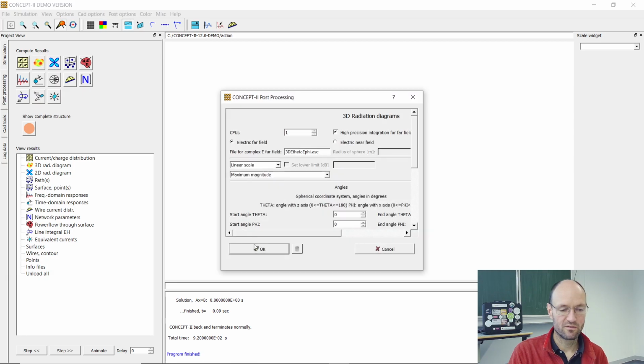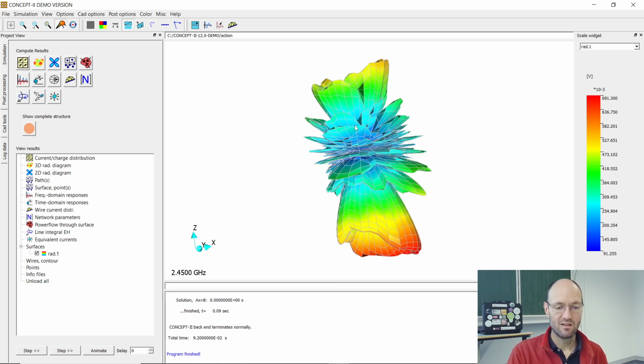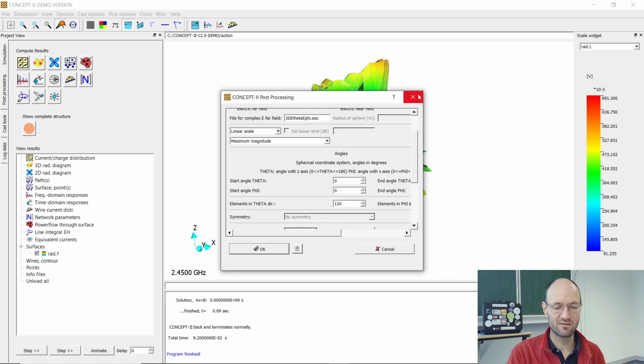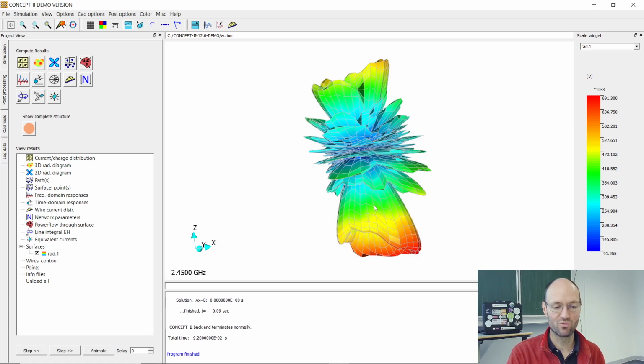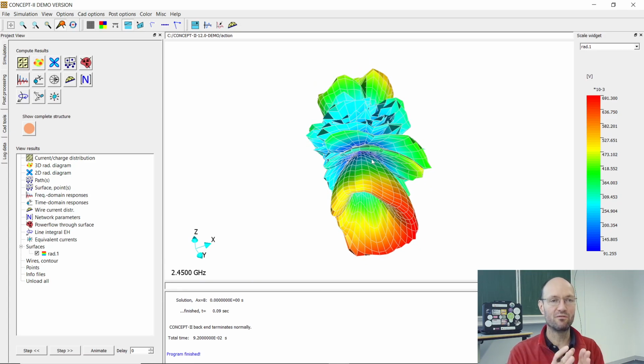So there's the radiation pattern. And now this gets very small and narrow lobes, and probably my display here is not sufficient. Probably I would need to have more steps for the theta and phi direction, but then it's too much computational effort for my computer to do it. So the radiation pattern gets very small and very narrow lobes, and it really takes time to do these small, narrow turntable steps in the semi-anechoic chamber to find the maximum emission.